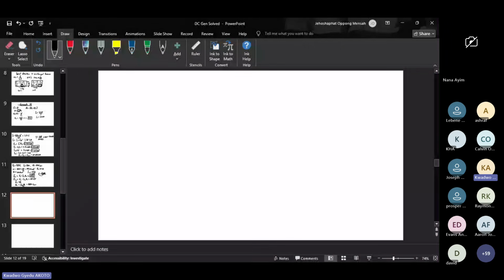So now let's look for power. We know that at electromechanical conversion, mechanical power is equal to electric power, right? So looking for the power at this load is just EB2 times IA2. We found EB2. We were given IA2. P mechanical is going to be 10.5 kilowatts, right?